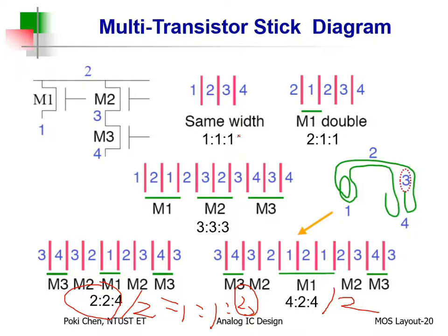And what is the third recommendation? According to MediaTek, for critical devices, they hope we can achieve the layout for second order common centroid. How to make it? Similarly, you divide all those by 4, right? So do it for the 50%, 25%, then reverse it for the other 25%, right? Then that is the fourth segment. You do the second segment with the reverse order. That's it. Okay? What I'm talking about?